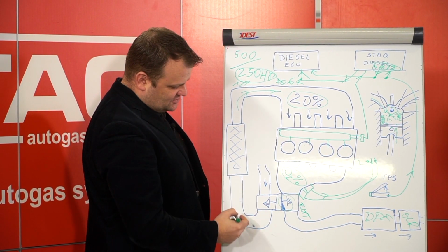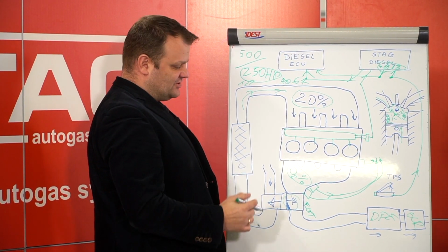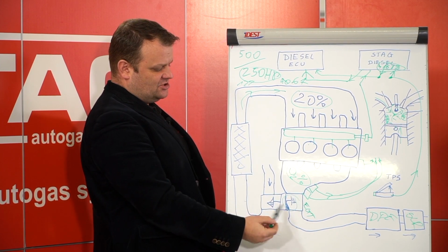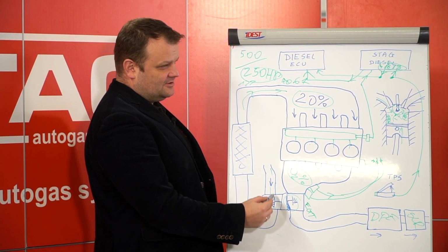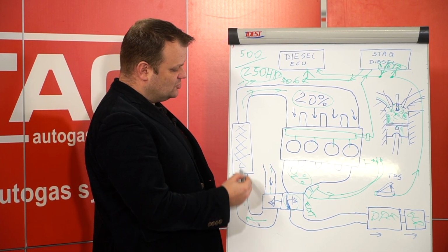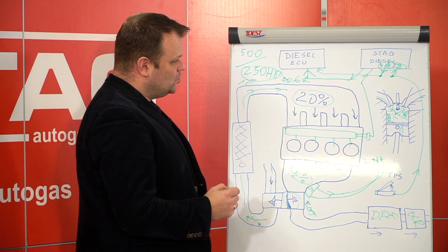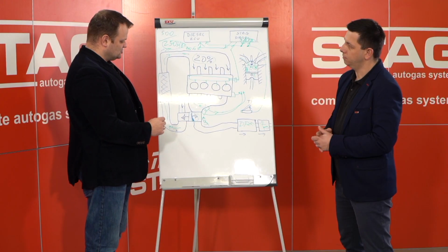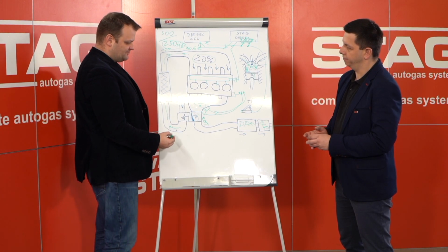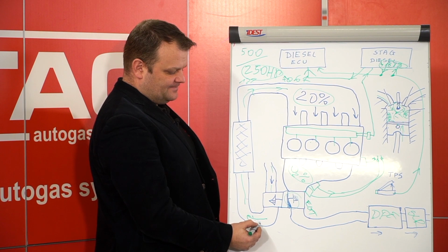So the trail should be as long as possible. Usually in the construction of an engine with a turbocharger, the fresh air goes to the turbocharger, then the heated air goes to the intercooler. I think the most effective place to put the nozzles is just before the intercooler.